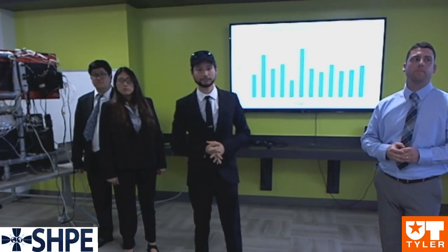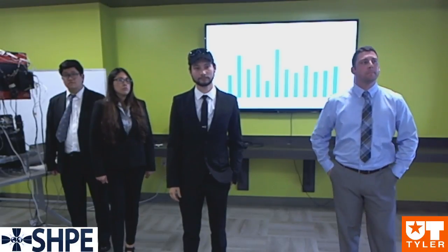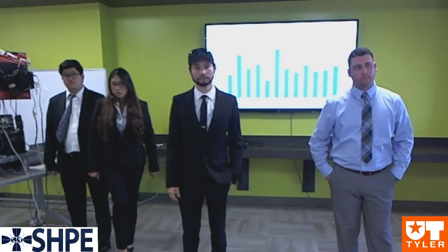I think Tony makes a good point. I agree, because this is measuring concentration, so it's not about flow. The point that you have water in the line, like you're saying, the water vapor shows there's only concentration changes. And one thing I didn't realize is that you're doing one sequential test. So that means whatever is in the line, you're using the same line to do multiple different samples, correct?